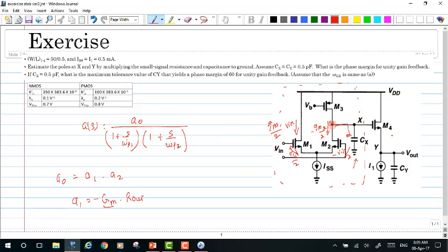We have learned all of this already. Now, taking this current into account, one could say that the capital GM for this circuit, or the first stage, is GM1 by 2. That is the value of GM we get out of the first stage.